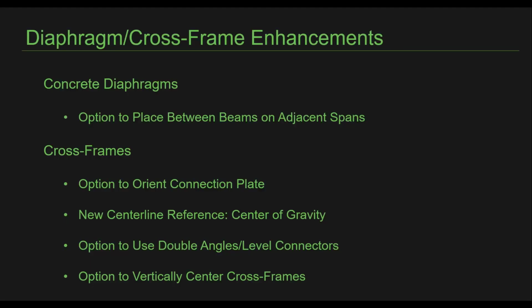In this video, we will review the diaphragm and cross-frame enhancements in the latest release of OpenBridge Modeler. For concrete diaphragms, the enhancement is that now they can be placed in between beams on adjacent spans. For cross-frames, a new option is introduced to adjust the orientation of connection plates.